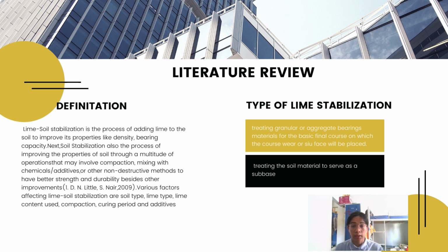Okay, for the second, the types of lime stabilization, there are two. Number one is treating granular or aggregate bearing material for the base course on which the course or seal face will be placed. And next, treating the soil material to serve as a sub-base.